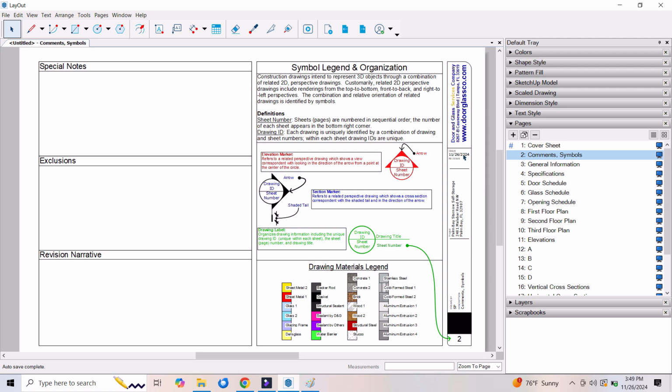You'll notice in the title block we have an issue date. That's going to be an Autotext type of a variable called current date. So that's going to print what it prints. And then we have a reissue date. So we could go in our Autotext and we could update the reissue date. The issue date, that is the original issue date, never changes. If it's reissued subsequently, then you just put additional dates. Every time you have a revision, you'll add a new date. So you could end up with 3 or 4 different revision dates.